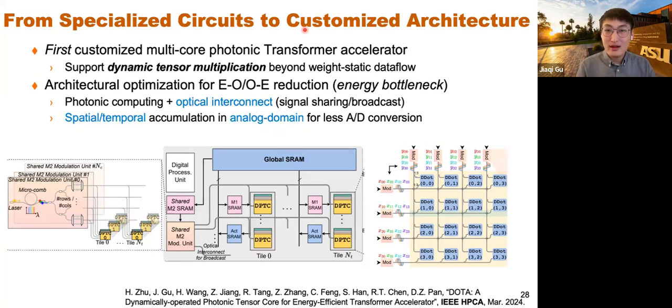In your neural network training, to replace FDTD, what are the spatial and temporal step sizes and your neural network matrix size? First of all, we're not replacing FDTD, it's FDFD. It's not a time domain simulation, it's frequency domain FDFD, so we don't have the temporal step size. We're solving the steady state field. We only have the spatial matrix size.